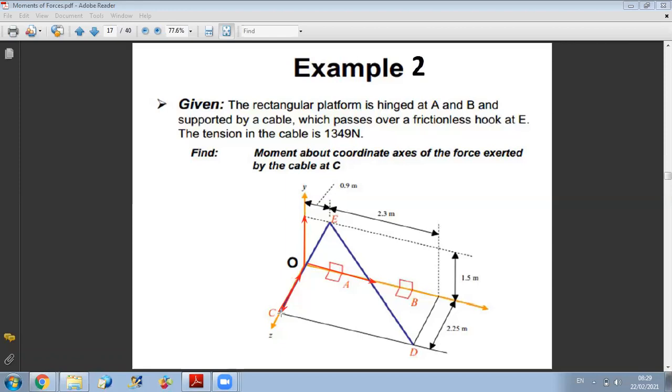The component of the vector along i will be the moment of the force about x-axis passing by O, and the component along j will be the moment about y-axis passing by O, and finally the component along k will be the moment about the z axis. Okay? So the technique here, in order to find the moment about the three axes, is simply to say, I will find the moment of this force about point O.